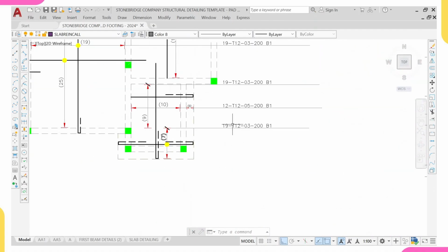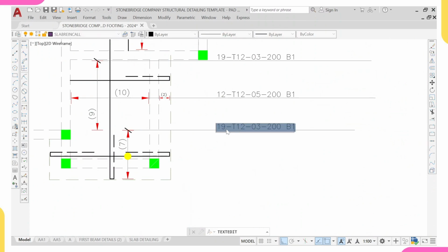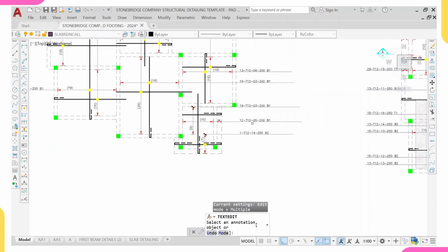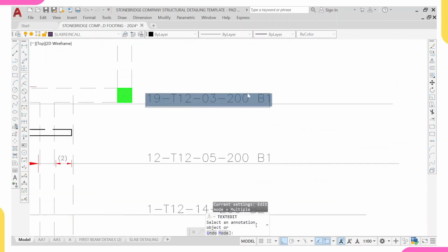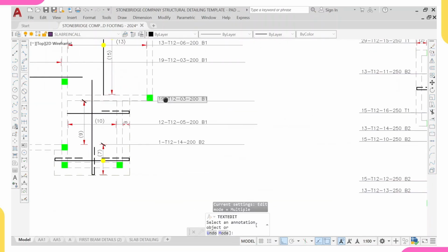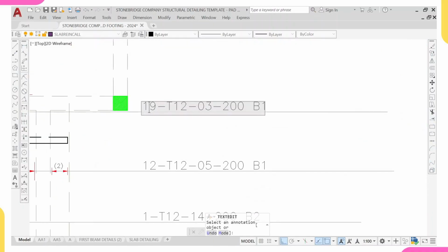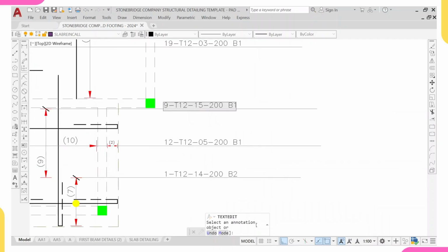This one is having 7 numbers. So I'll double click on this, then delete. 7 numbers, 7. Our last bar mark is 13, so this should be 14. Then remember, this is B2, not B1 again, B2. So this is what I'm having at this point. I'll also come over to this point. This thing now is what, how many in number? It is 9. So I'll just come and erase this. Then this should be 15, and this should be 2.